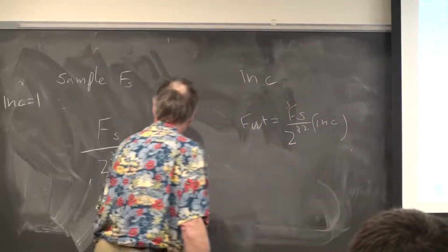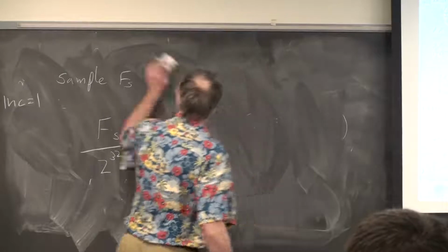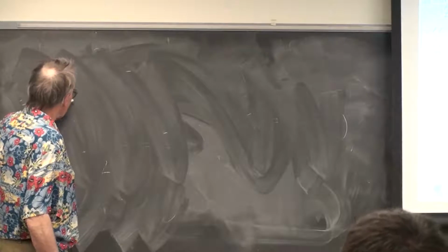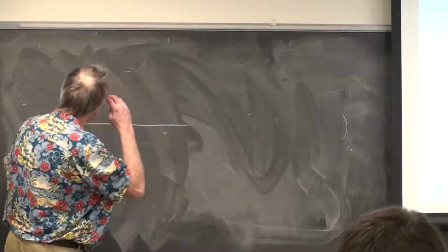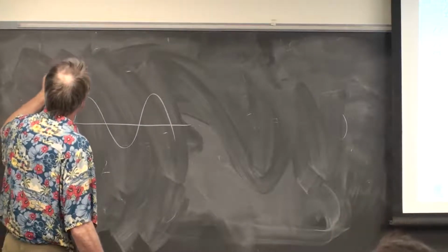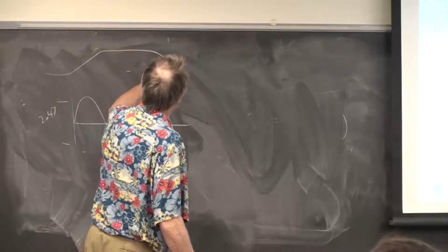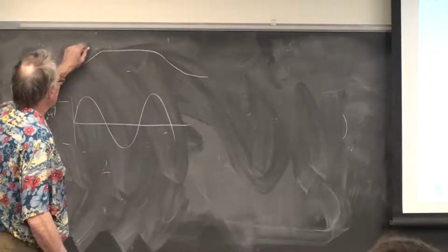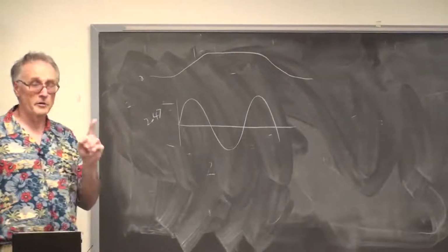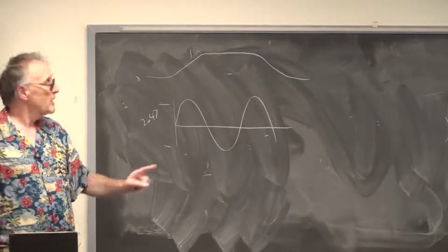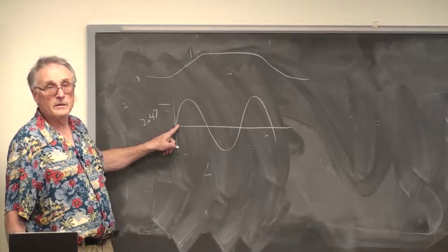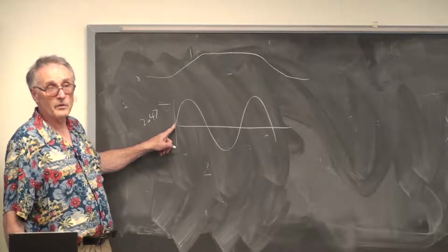So the sine wave, the mathematical sine wave, is going to be plus or minus 2047. Your envelope is going to look like this. Starts at 0, goes to 1. It would be nice if when you did the multiply of 0 times 0, you got 0. One way to do that is to make sure that the entry here is 0 and not plus 2047.